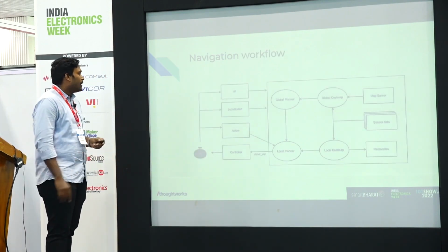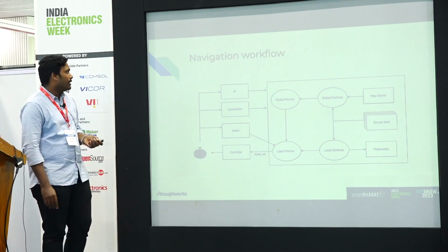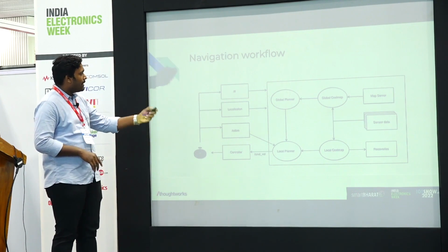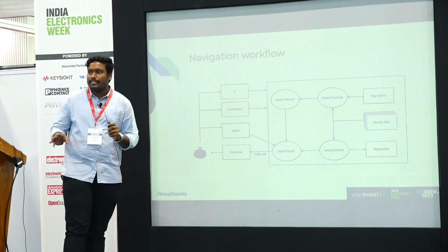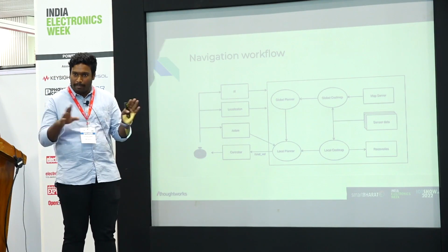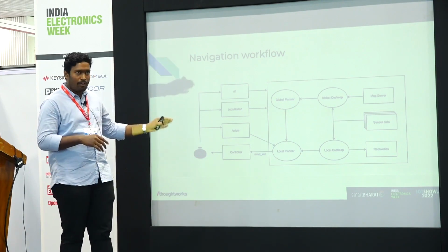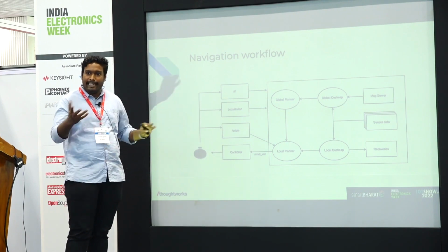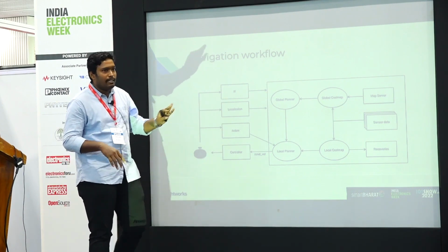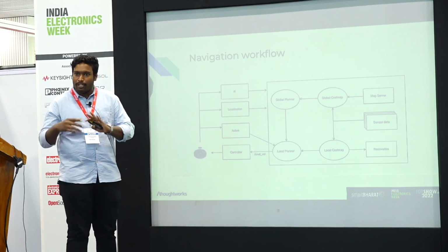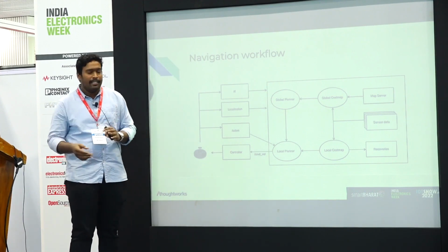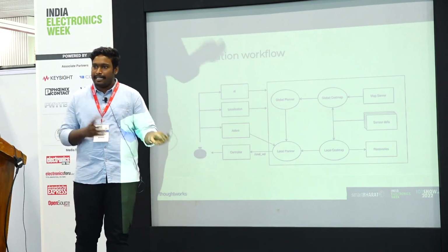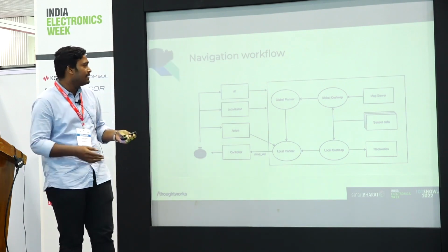Okay, so here, this is a high level workflow of navigation. I would like to start from the right, where you see the map server. The map server is nothing but the data about your map that you already collected. The components we have been talking about, like cost maps and planners, need that data, and in real time they also need data from your sensors. Depending on the condition, you have various sensors like LiDAR, depth cameras, range sensors, IR sensors, and other things.